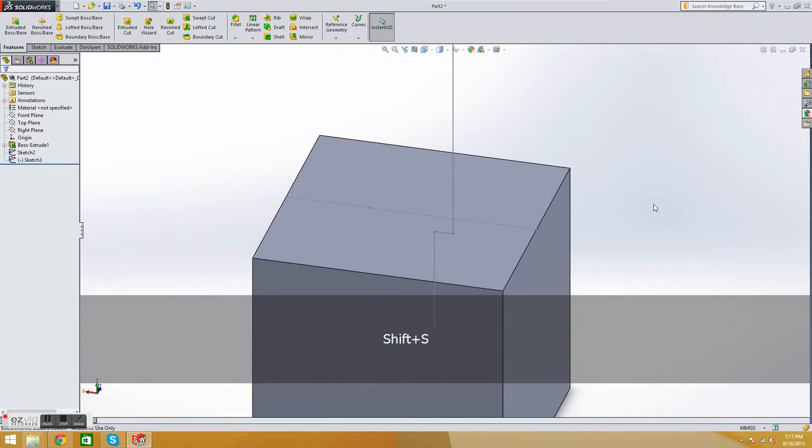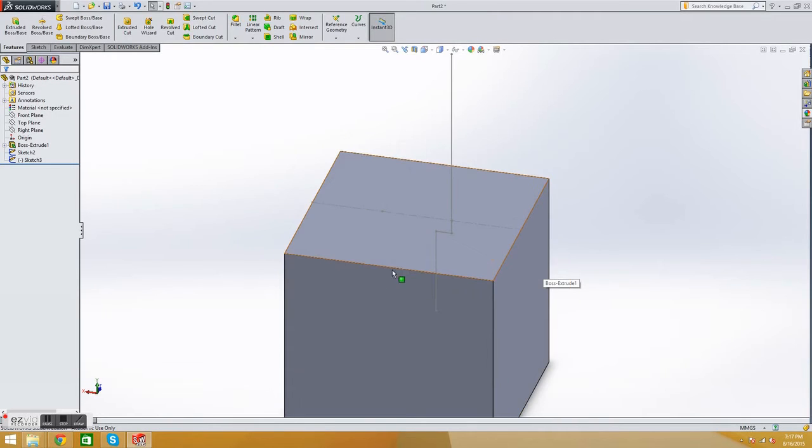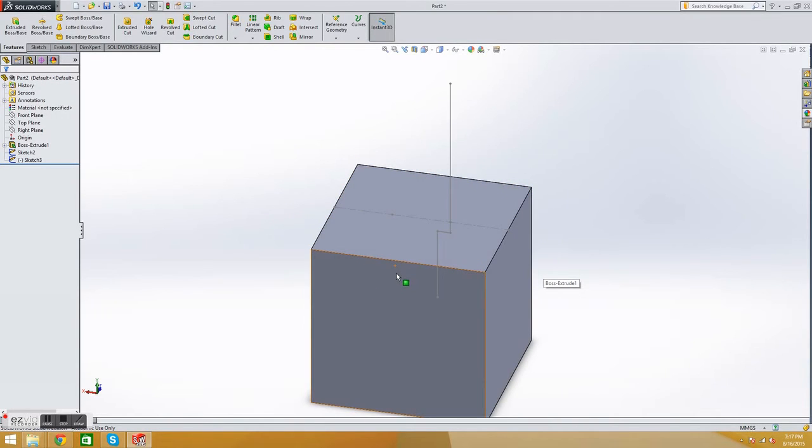Alright. Now what you want to do is make 3 axes. You have these planes, your main planes, but we want to make reference lines. Because when you have this sketch here, you want to revolve it in a circle, but SolidWorks won't know which way to do that. You could revolve it around anything. So what you have to do is make axes.